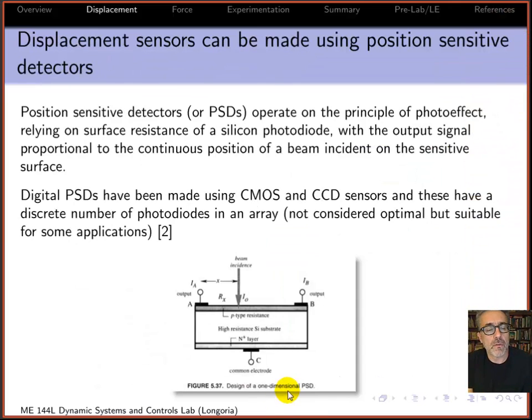We've recently started using another kind of displacement sensor in the lab to measure, in this case, beam deflection, and this is a non-contact type sensor. The LVDT core sits on the beam. The nice thing about some of these laser-based sensors is that they're non-contact, and they use position-sensitive detectors.